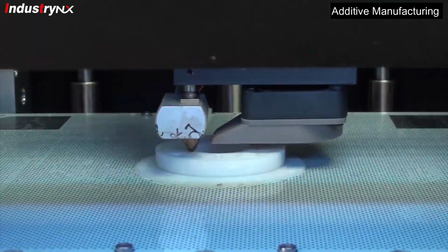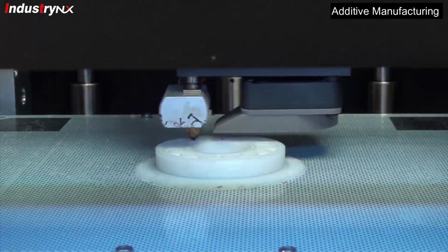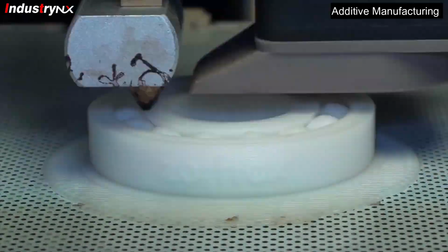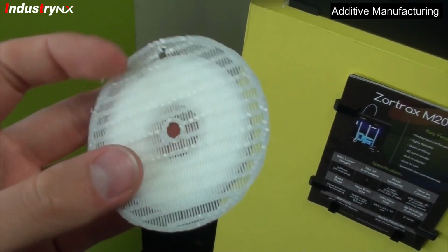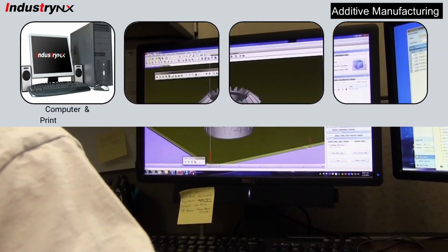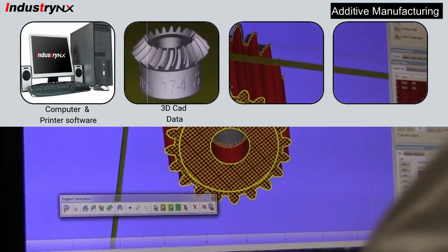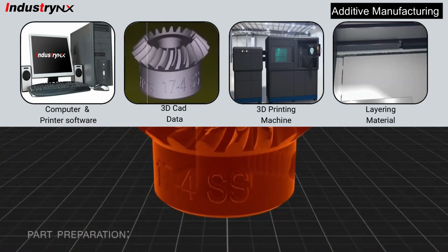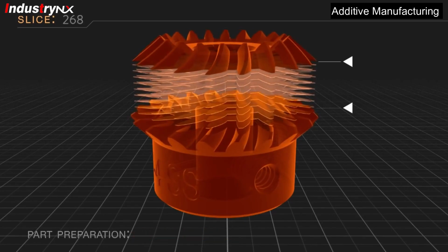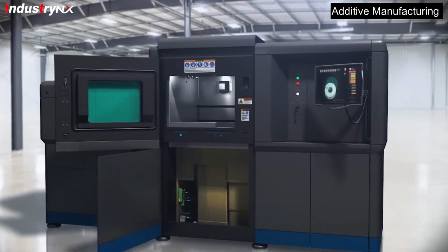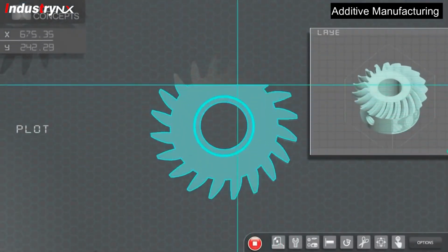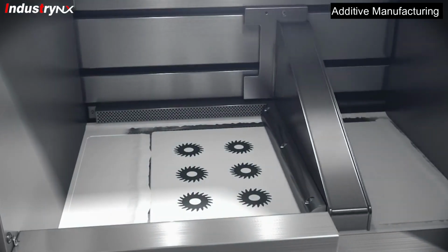Additive manufacturing is an appropriate name which describes the technology of building 3D objects by adding layer upon layer of material, whether the material is plastic, metal, concrete, etc. It is also called 3D printing. AM technology uses a computer, 3D CAD software, machine equipment, and layering material. Once a CAD input is given, the AM equipment analyzes data from the CAD file and lays down and adds successive layers of sheet material, liquid, powder, or other, layer upon layer, to print a 3D object.